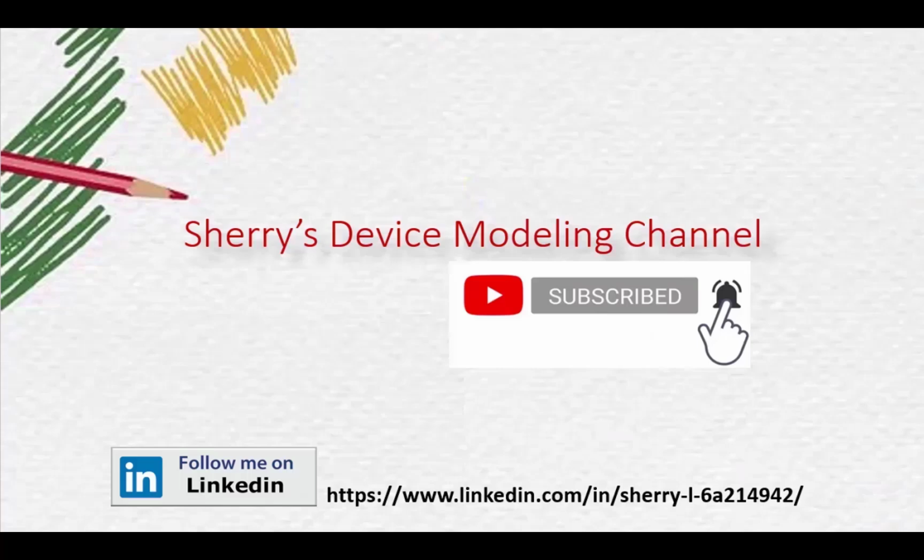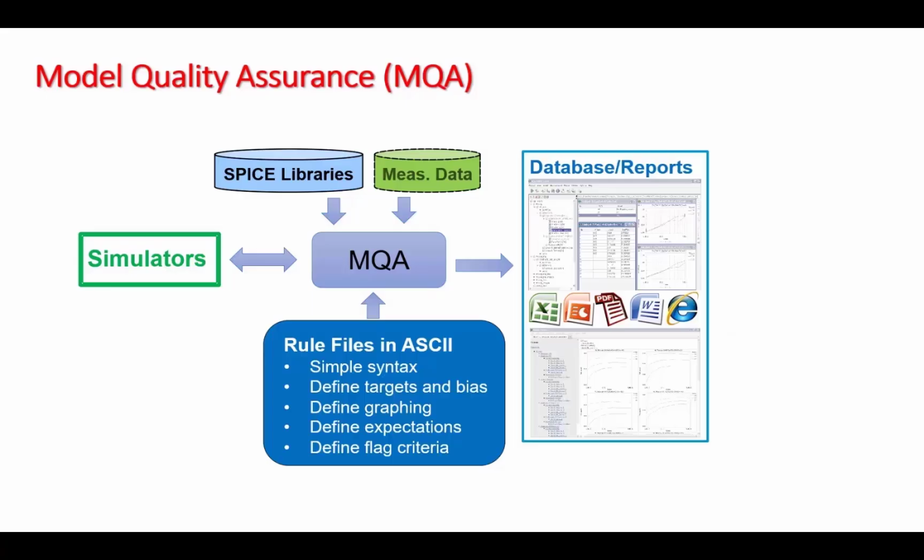The QA process of the whole library is complicated. The library usually includes lots of devices and multiple corners, and there are lots of items that need to be checked, like accuracy, model trend, parameter range, corner cross, corner range, etc. So if you do the QA work manually, it takes a lot of time. Since the QA includes lots of repeating simulation and plotting work, if we can do it through a tool, it will make the work much easier. MQA is an industry standard model QA tool. Now let's look at MQA together.